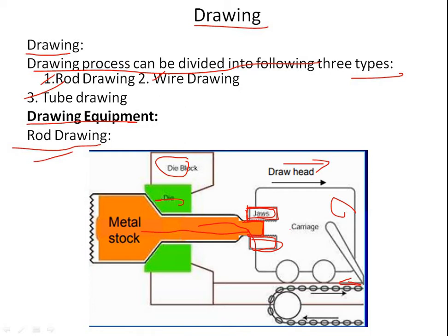It is then washed with water and dipped in an emulsion of slaked lime and water. This neutralizes the acid, and excess lime dries on the material surface and forms a base to absorb the mineral oil or the grease, whichever it may be, the lubricant. Soap can also be used as a lubricant, but results in a dull surface of the finished products.